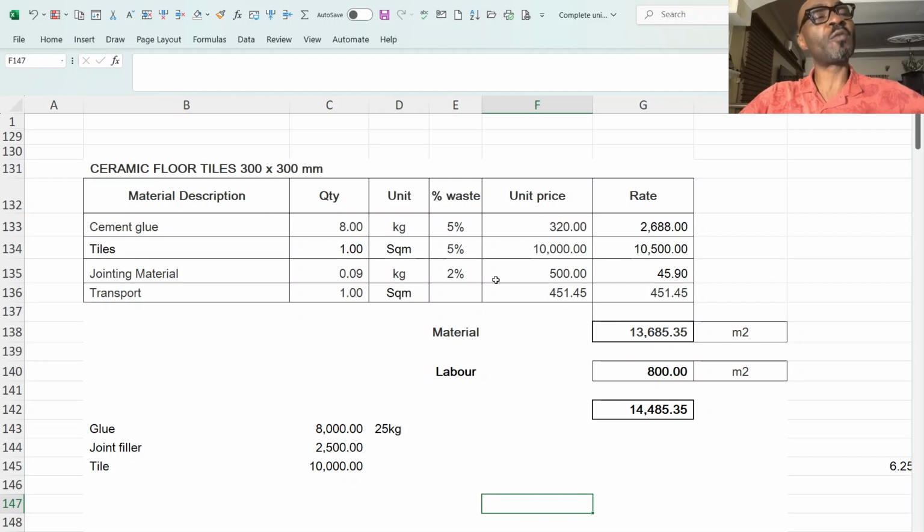If you have too much undulation, those undulations have to be filled, and they will be filled with the cement glue. If the screeding is properly done, then of course the dosage will suffice. But if it is not properly done, there is going to be a problem, because you're going to have wastages used to fill in those undulations.